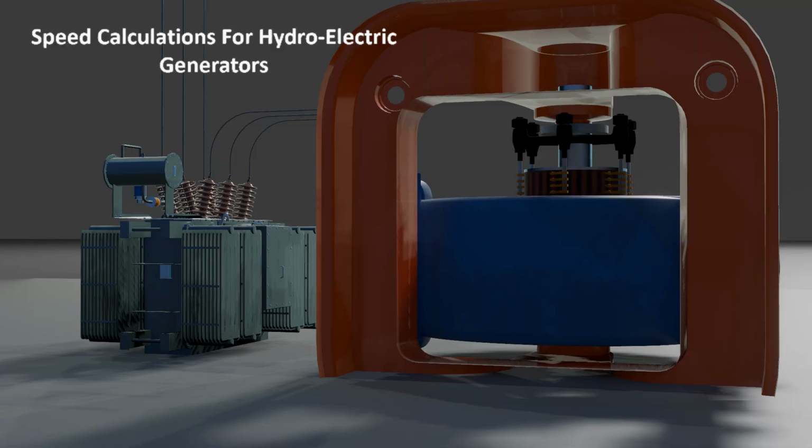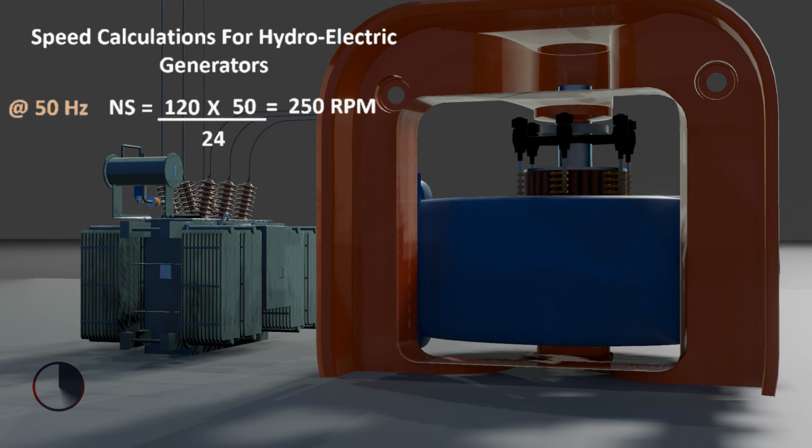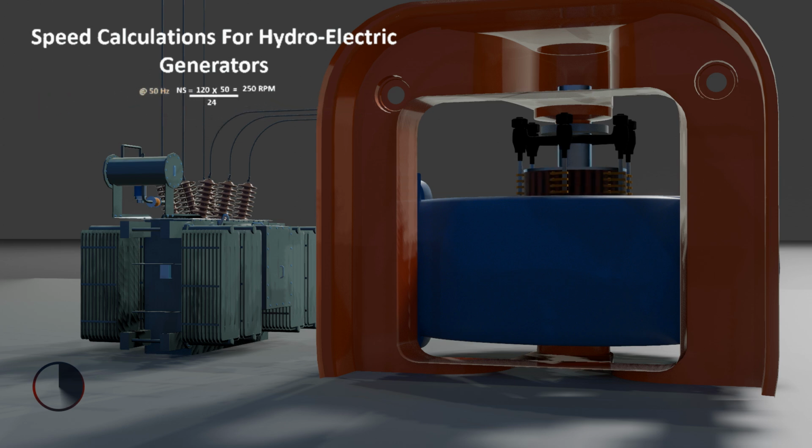Which we can work out as 120 multiplied by 50 Hz all over 24. This will equal 250 revolutions per minute. Also, if the same calculation is done when the required frequency is 60 Hz, the speed will be 300 revolutions per minute.